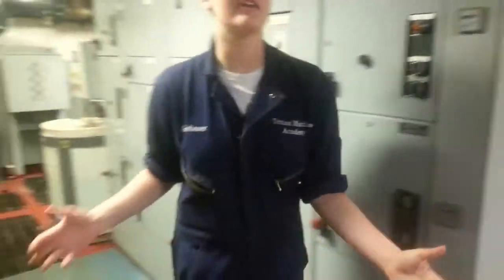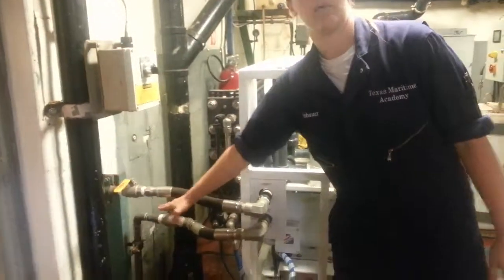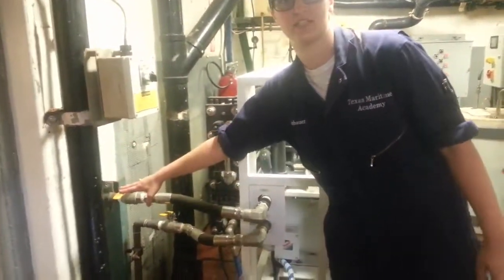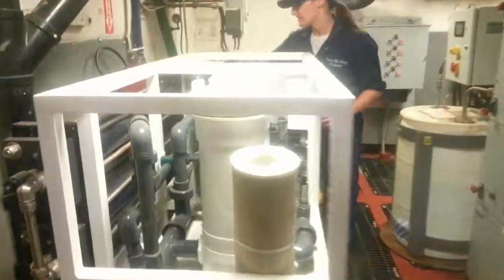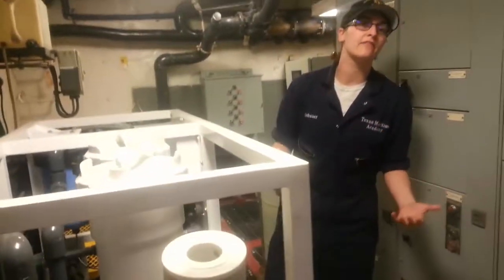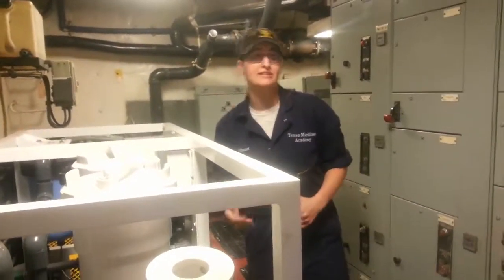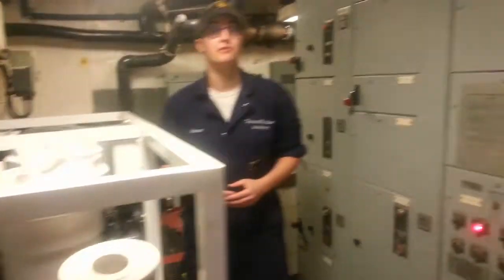And so before you turn it on, you have to make sure all these lines that I mentioned are open. So you have to make sure your saltwater supply is open, brine discharge is open, your back flush supply is open, and then your potable water discharge has to be open. Here is the valve for potable water discharge. If none of those valves are open and you energize it and go to turn it on, you'll trip the equipment or it just simply won't run.